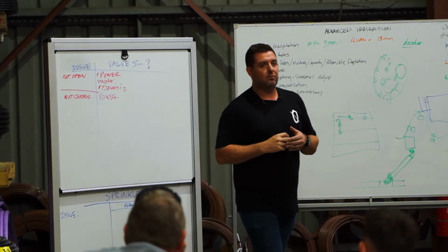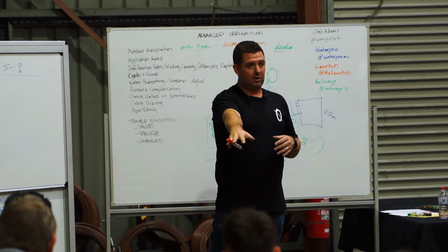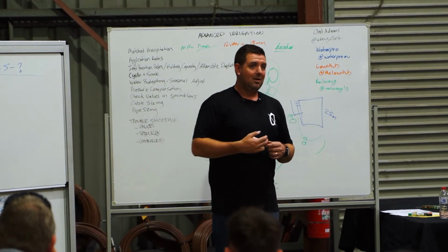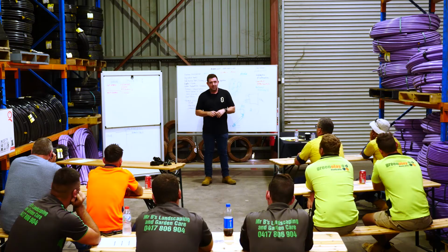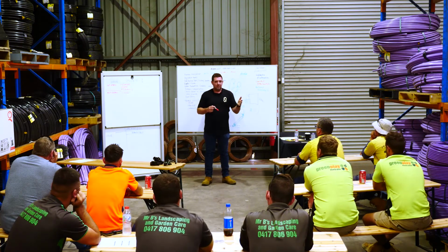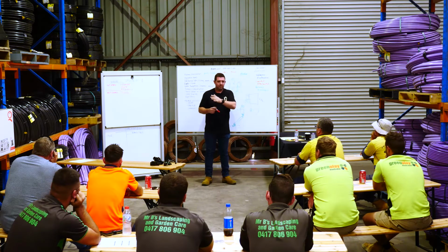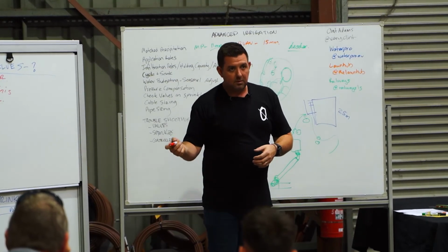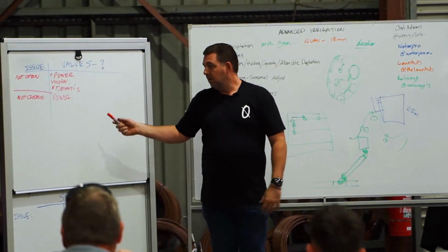The only reason a solenoid valve won't turn off from a power standpoint, when I'm talking 24 volt AC, is because the controller is telling it to stay open. So that's a programming issue. It happens most often when someone has 4 programs and 4 start times, and then they set it and it's just running and running and running, and the client thinks that it shouldn't be on, but the controller's been told that it has to be on.